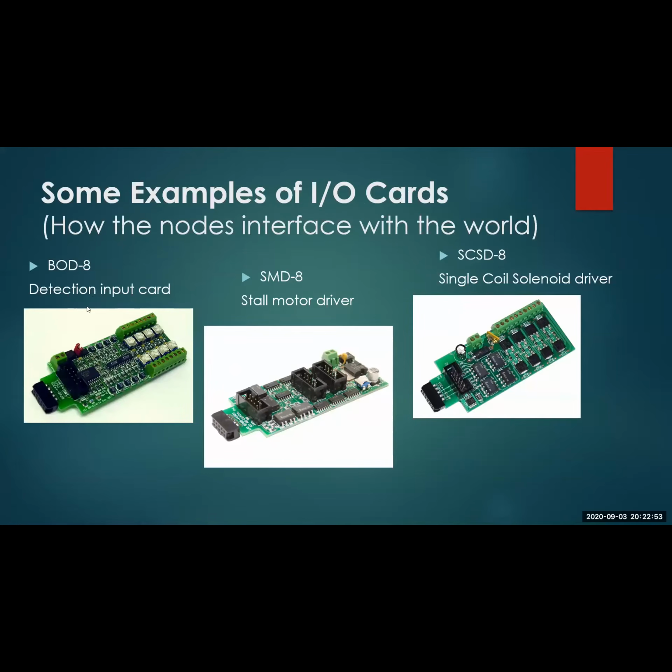We can tie them into what are called I/O cards or signal conditioning cards. The BOD8 plugs right into there. You can see the connector right there. You plug it right in, and now I've got 8 detection points that are pre-configured, ready to go. You just plug it in. It recognizes it as a detection input card. Now I've got 8 detection points for your blocks. The SMD, similarly, is 8 outputs.